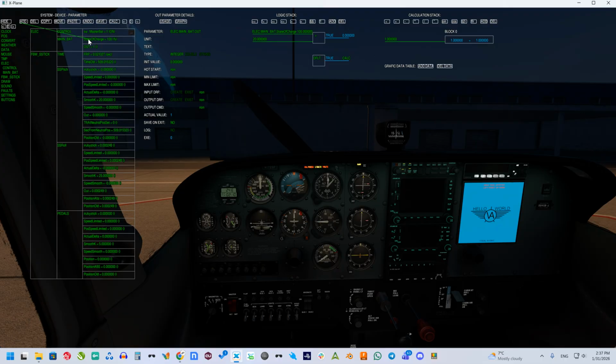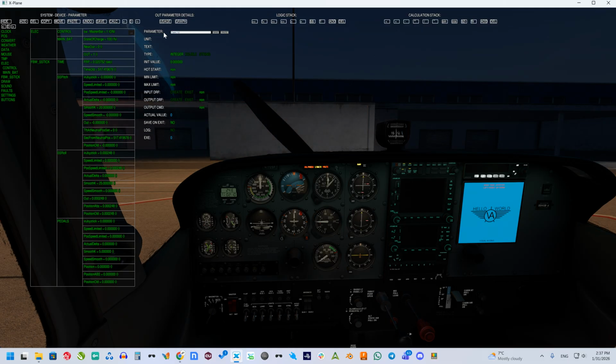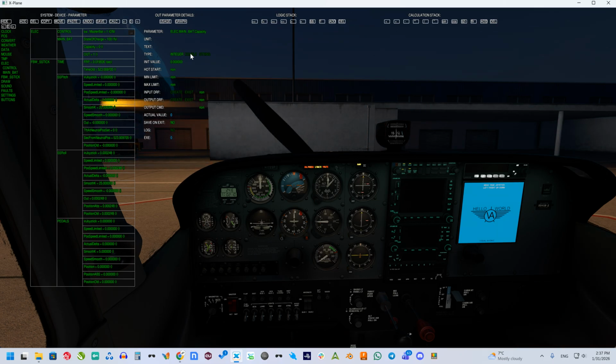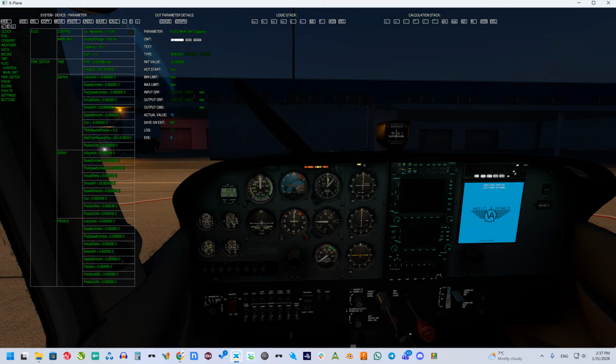Add a new parameter, name it capacity, and its value will be, I think, about 15, and the unit is ampere hours, AH. So like this. Good. Out is just 1 or 0. Good. I want to save our work.